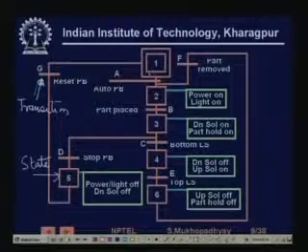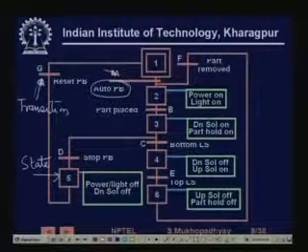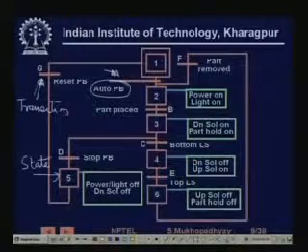You see that the double square means that it is the initial state. Initially, if the auto push button is pressed, transition A gets activated and takes the system from state 1 to state 2. So, this is the transition condition. You can have much more complicated conditions, but in this case we have very simple conditions. If this transition occurs, then the system comes to state 2.